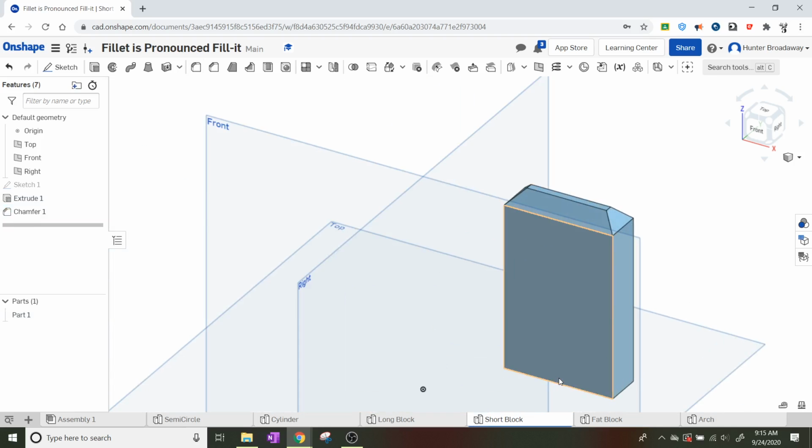Okay. Anybody have any questions about it? Try just one chamfer on it. I'm going to look around and see to make sure you're okay. Click on just one of your parts. Yeah, that one will work. Just go ahead and chamfer that one. Just make a chamfer on any one of them. It doesn't matter which shape you use. It's okay. We're just practicing. What, did you chamfer everything? Yeah, you chamfered everything. Okay. If you chamfer everything, it's going to make it look kind of weird, like a gemstone almost. If you chamfer all the sides, it's going to look very much angled. Yep, there you go. You're good.